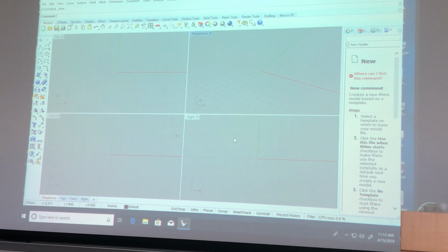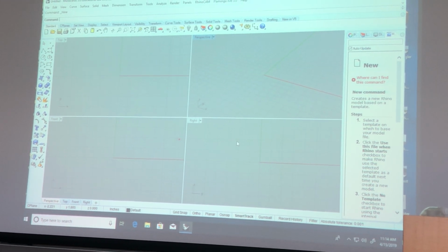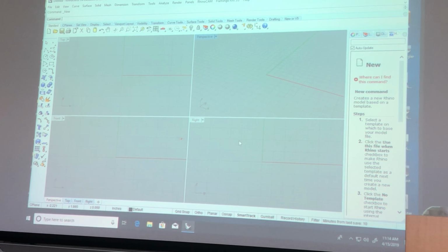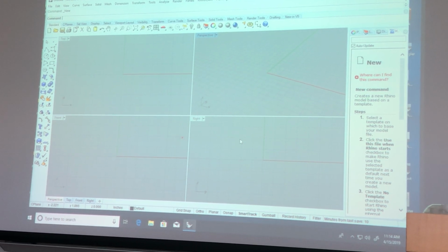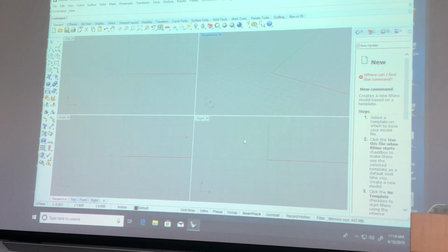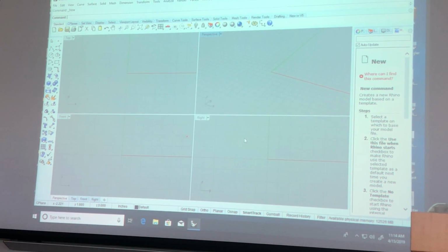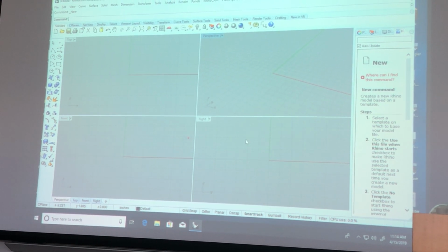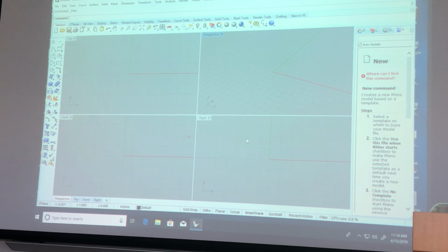So, if you can't print a wall that's less than 0.05 inches wide and you don't want to do the math, then you need to draw the wall at the printable width in Rhino. That's all. It's 0.05 or more.